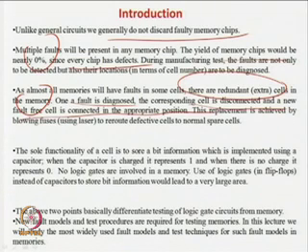So, how do you do it? Sometimes we do it by a multiplexing arrangement, and sometimes we achieve it by blowing up some laser fuses. So, you find out that this circuit is not working properly, and the input and output connections to the cells can be blown off by using laser cutters or something of that kind. Sometimes you can have demultiplexing or multiplexing chips, and you can permanently select or deselect, say for example, this is the input, which is input to the faulty memory cell. This is for the good cell.